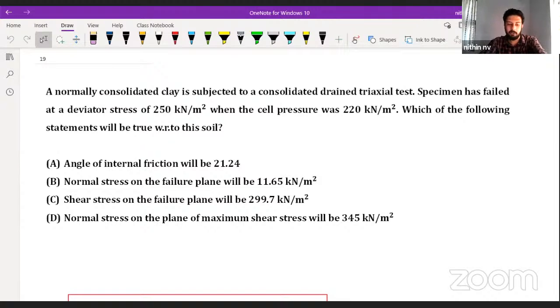Yes, natural logarithm will be used in permeability, the variable head test, and also in well hydraulics. We have discussed that in the hydrology irrigation session. You can watch that. In well hydraulics, for checking the yield of an aquifer, there also we can use natural logarithm. Wherever we use natural logarithm, in the same place we can use log base 10, but 2.303 will come extra. If you see 2.303 somewhere, it is the conversion of natural logarithm into log.